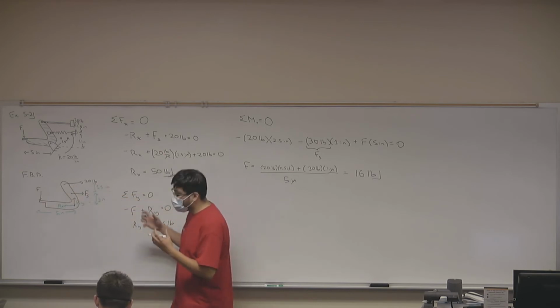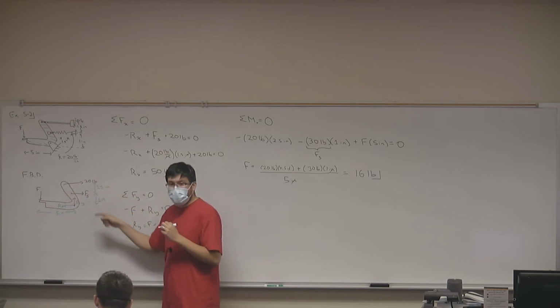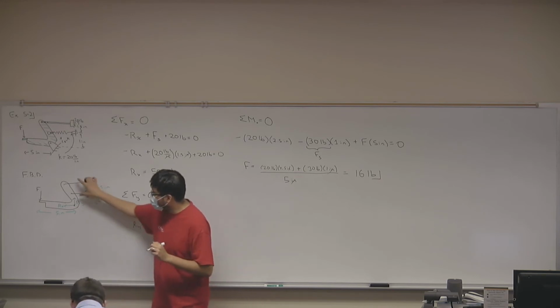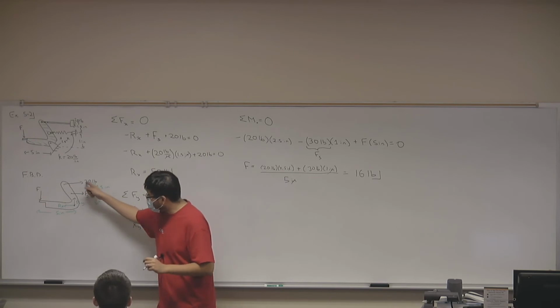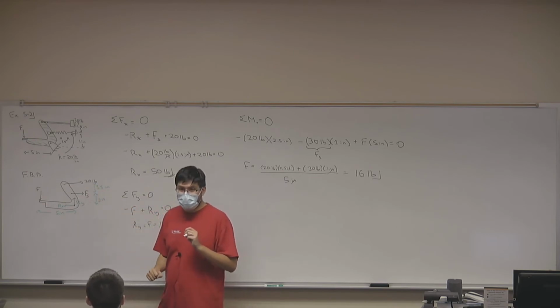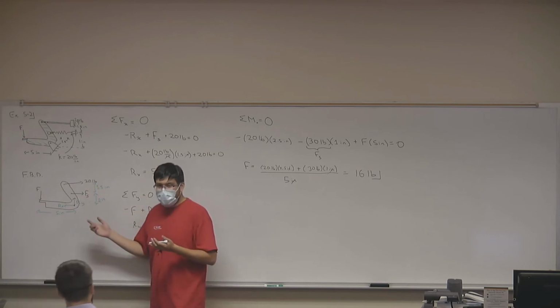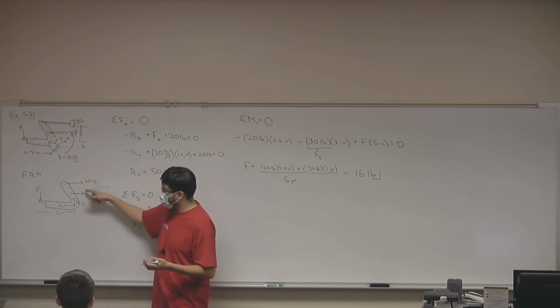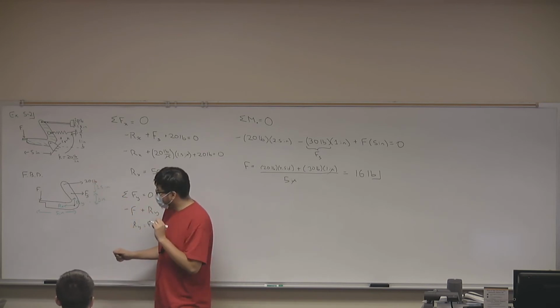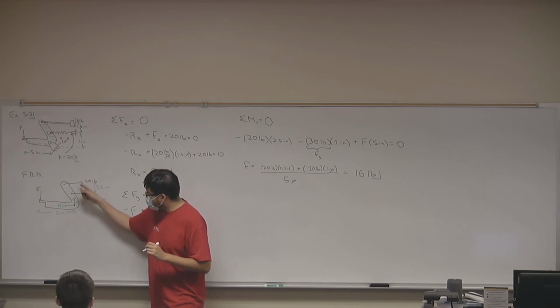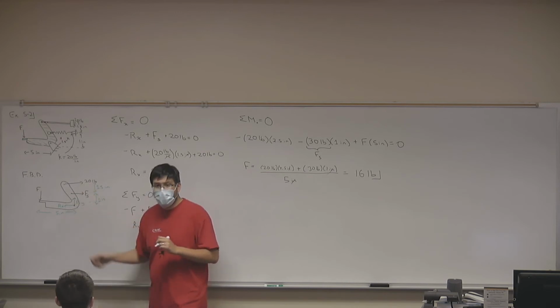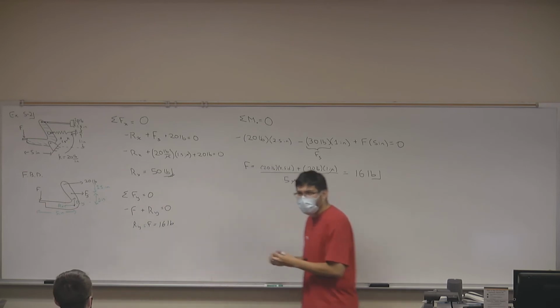So if I want to reduce these two forces, what I can do is express them as only one 50-pound force instead of a 20-pound force and a 30-pound force, right? Okay. So it's easy linearly, right? So I can reduce my forces to a 50-pound force, but in order for that reduction to be complete, I need to figure out if this 50-pound force can cause an equivalent moment. It's actually not that easy. Let's go ahead and look at it, okay?